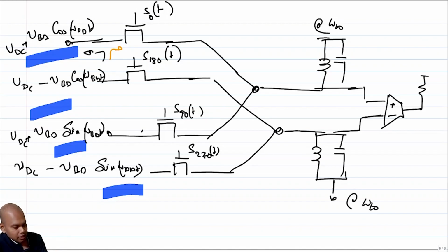This essentially is giving you an idea of an up conversion. This is doing an up conversion through a set of passive IQ mixers, right? So this is quite simple and it works. But the important thing to note here is that this only works if there is no coupling between the in phase path and the quadrature path.